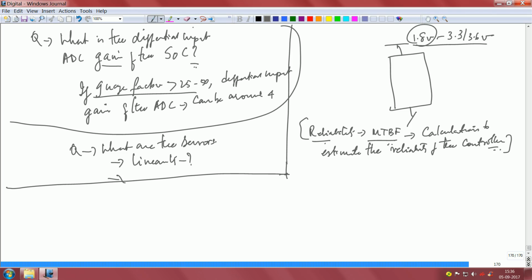Here we are not talking about any vendor, irrespective of any vendor you must do this reliability calculation, use the MTBF, mean time between failures from the data sheet, and estimate the reliability of the controller of your choice. So this is another thing, if it is a low reliable thing, do not choose that, okay. You put a bar and say it should be so much reliable, and only then I will actually use it in my applications.